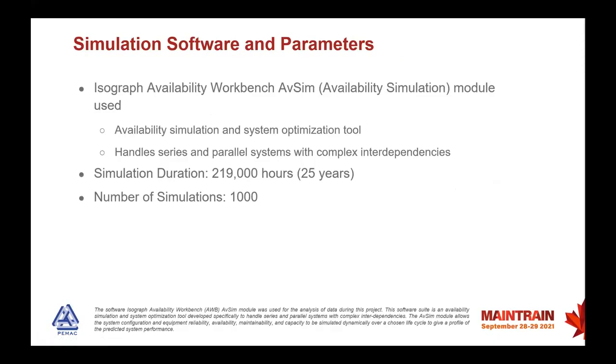To give you a little insight into the simulation software, Isograph's Availability Workbench Availability Simulation module, or AVSIM, is what was used for it. It's an availability simulation and system optimization tool, and it handles series and parallel systems. It's able to handle some pretty complex interdependencies pretty well. All durations are in hours within the software, so the simulation duration was 219,000 hours, or 25 years, which is the expected life for this facility.